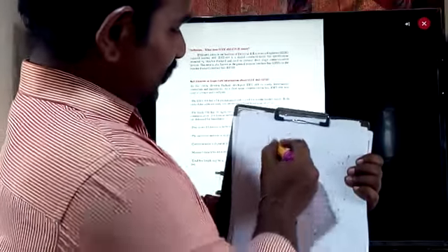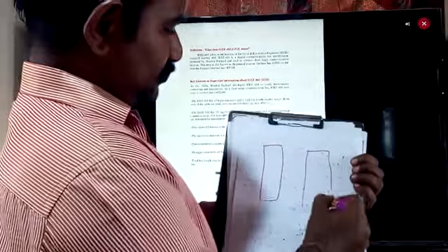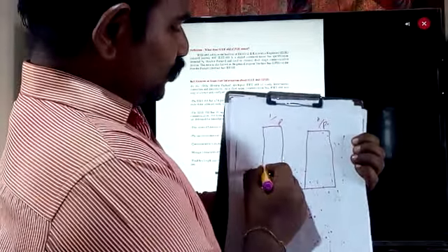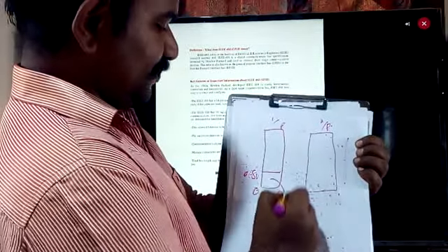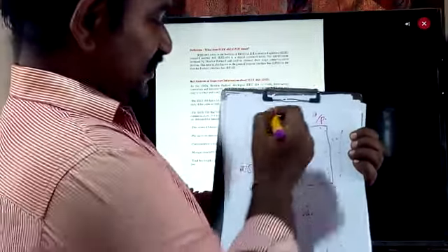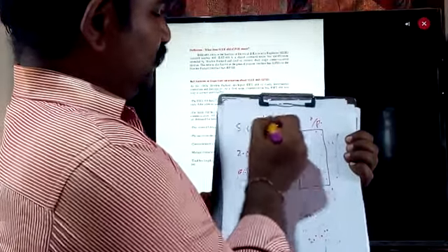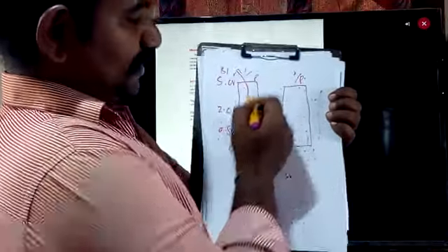So the TTL family is supporting the TTL standard. TTL family means I am going to take the voltage range. This is for the input, this is for the output. So 0 to 0.8 volts is treated as a binary 0 for the input case. 2.0 to 5.0 volts is treated as a binary 1 for the input case.